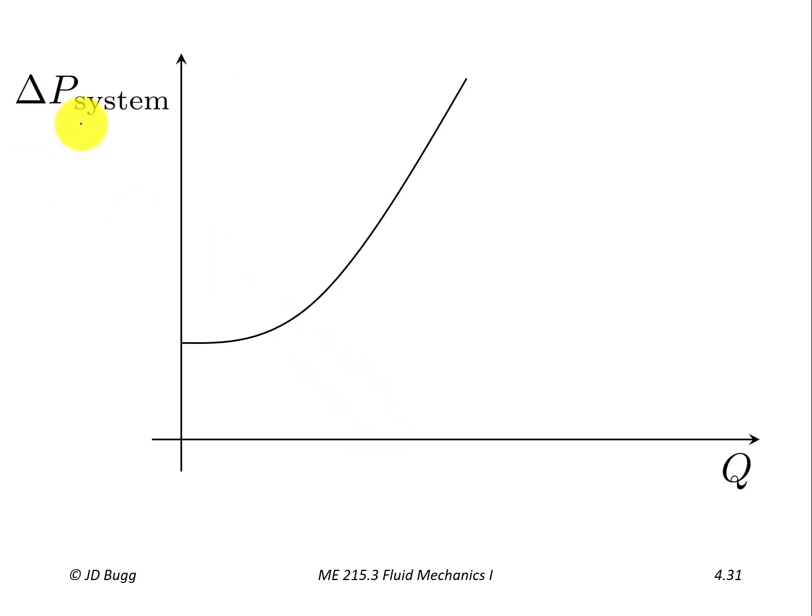So a system curve, which is what we're seeing here, is a plot of this system pressure versus the volume flow rate through the piping system. And as we saw on the previous slide, that's going to be a parabola. So this particular parabola has a fixed system pressure equal to that amount, and its variable system pressure is the portion above this location here.